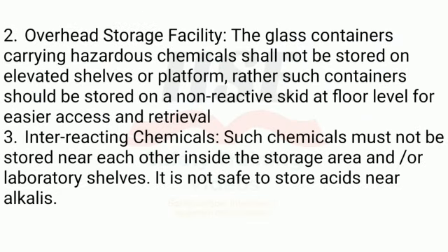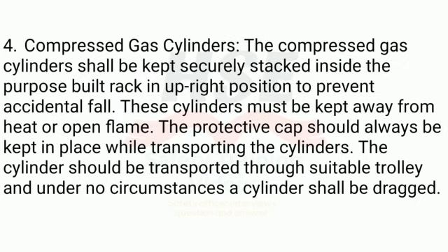2. Overhead storage facility. The glass containers carrying hazardous chemicals shall not be stored on elevated shelves or platform, rather such containers should be stored on a non-reactive skid at floor level for easier access and retrieval. 3. Interreacting chemicals. Such chemicals must not be stored near each other inside the storage area and/or laboratory shelves. It is not safe to store acids near alkalis.